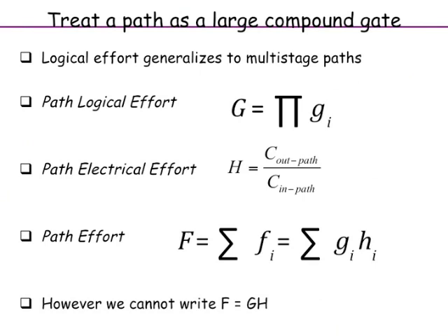So as a designer, really you don't get down to the level of figuring out the sizes in that type of scenario. But if you're not meeting timing, you have to look at the architecture. Maybe you have to change the amount of pipelining, maybe you have to do things in parallel.